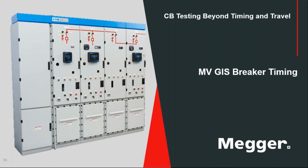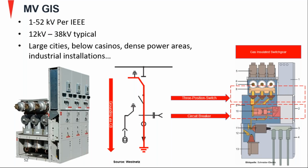As I mentioned before, what is characteristic of any GIS switchgear, or gas insulated switchgear, is that there's no access to the terminals, because everything is insulated, everything is covered, and you don't have access to the actual terminals of the breaker, and then testing becomes difficult. You would have to disassemble something to be able to test.